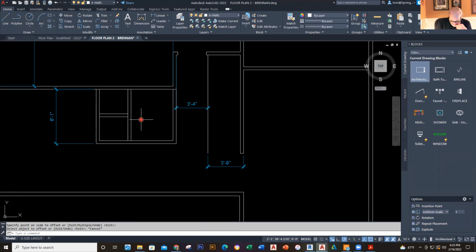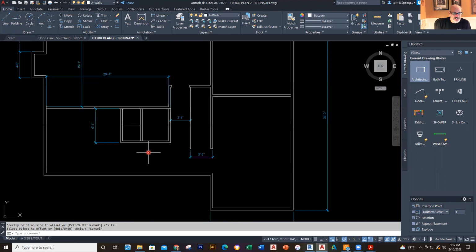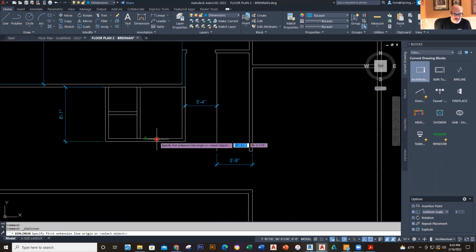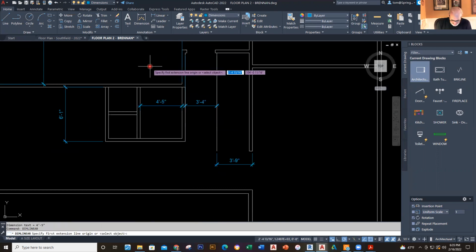And then I could actually begin to place some different doors and so forth. Now that I got these in place, I've got the basic geometry constructed here. I'll put a couple more dimensions in here just to prove the concept, and then we'll move on from there. What this dimension should be from here to here, as I see it, is 4'5". That's exactly right. And this other one should be going from the inside, here to here. That should be 3 feet, and it is. So we are good to go there. We're looking pretty good here.